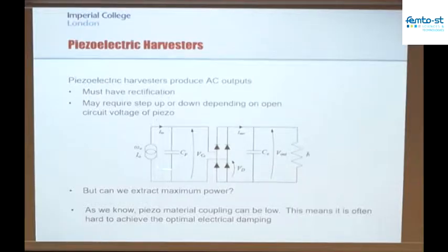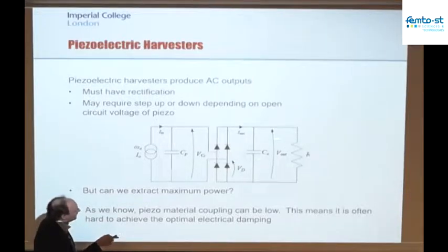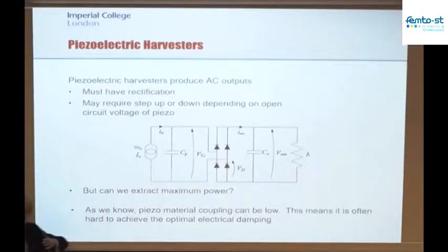Now, if you have this sort of system here, the only way you can control the voltage that you see on the capacitor is by directly controlling the output voltage here. And you might not want to do that because this output voltage is feeding the load, and you probably want to decouple the voltage that the load sees from the voltage that the transducer sees. In addition, with this circuit, it's got two diode drops that I have to overcome.